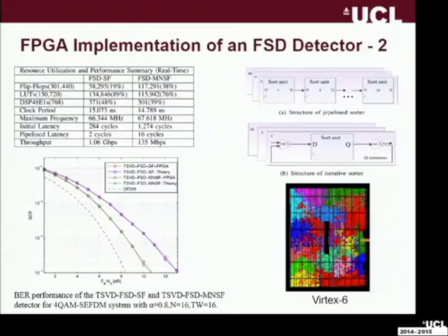And then in terms of performance, if you used it in its purity without the modified real value decomposition, you can see here there's almost a 2 decibel degradation in bit error rate performance. So this is with the sorting stage at this speed, or without the sorting stage at that speed. So again, trading off speed with complexity.